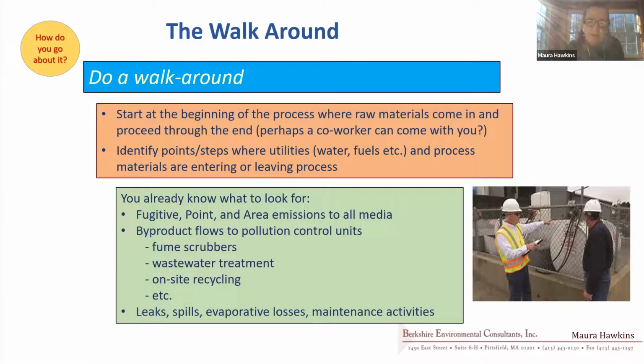the process. It's one thing to look at it on a process flow diagram. It's another thing to see it in person, where it actually comes in, how it gets in. Is there a port on the outside of the building where a truck drives up and you do bulk unloading? Is there a hose that goes into a tank inside the building? Understanding all of those things and how they actually happen in the plant is important.